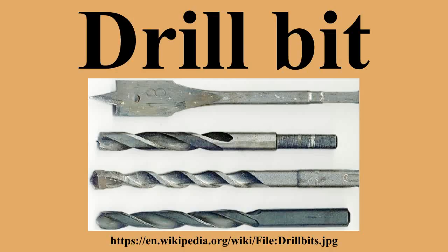The finished hole can often be made quite smooth and burr-free, especially in plastic. An additional use of unibits is deburring holes left by other bits, as the sharp increase to the next step size allows the cutting edge to scrape burrs off the entry surface of the workpiece. However, the straight flute is poor at chip ejection, and can cause a burr to be formed on the exit side of the hole, more so than a spiral twist drill bit turning at high speed.